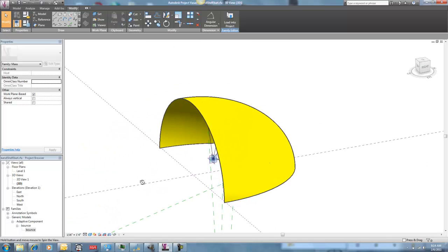And let's see, that starts to look like, well, it's not a huge sampling, but I can keep doing this. I can keep reproducing these points. If I just select all of them and then control drag, I can get a nice distribution of points all over my band shell surface. Oh, I was going to think about that for a second. And I can start to imagine what's going to happen if I have a shape like this and I have somebody talking in the middle of it.